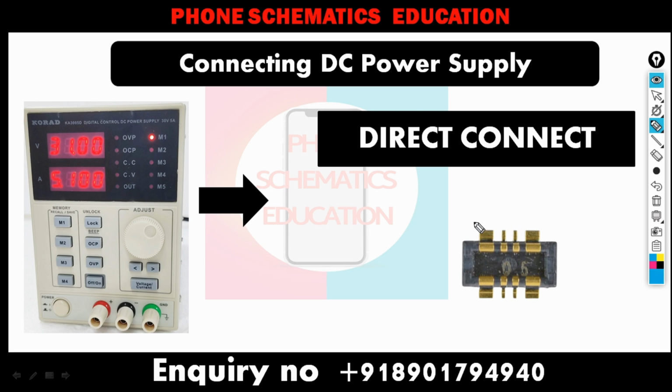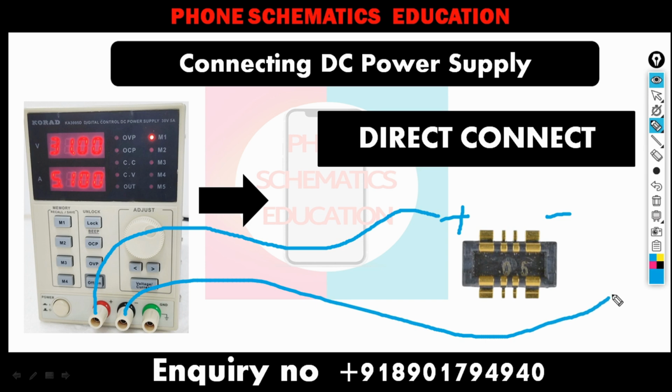First, through a multimeter, you can identify which pin is positive and which is negative. So you can connect the multimeter probe here. Also the banana probes: red on positive and black on negative. Also, you can find a TP on the motherboard on the positive line, like some of the points near the battery connector or the charging connector.